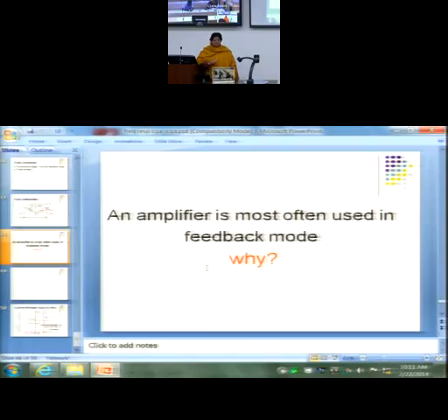What do you mean by fluctuations? Suppose I am designing an amplifier. I want a gain of 10. And if gain is depending on temperature fluctuations, voltage fluctuations, VT fluctuates, the gain shifts by plus minus 10%. So either sometimes I will be getting 9 or sometimes 11. Why not 10? Why 9 and 11? Why is there a window? I do not want this window. Can I say to my user, you will get a gain of 10, plus minus 0.1%? I need the window to be very, very small if at all it exists.